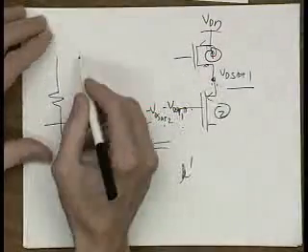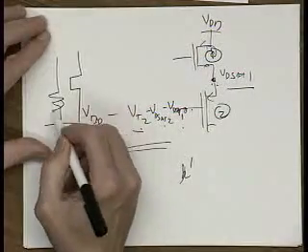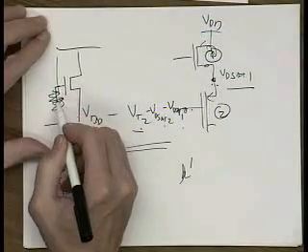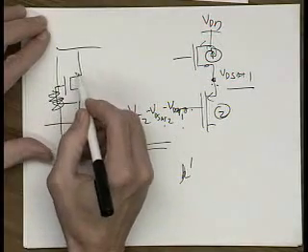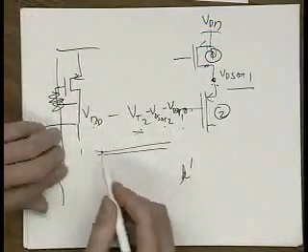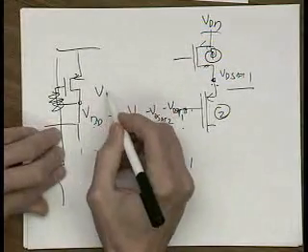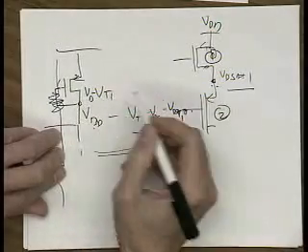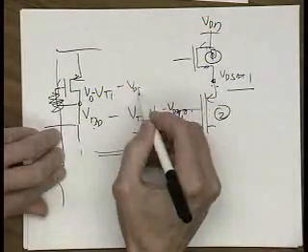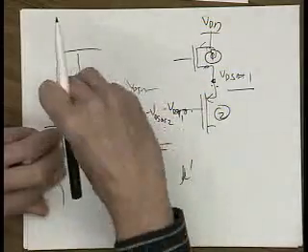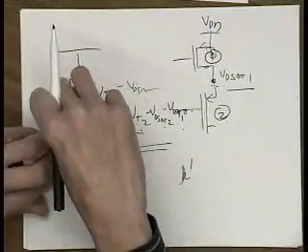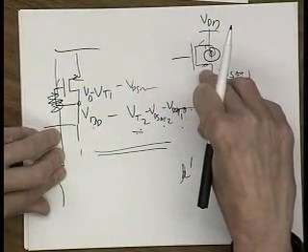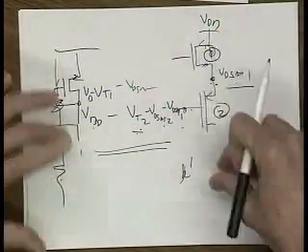On the other hand, if you make this out of some sort of transistor that's biased somehow or other, then this voltage right here is a function of the process. This will be VDD minus VT of this transistor, minus VD sats and so on. So if you make the circuit for your bias look like the circuit you're biasing, then you can get everything to track.